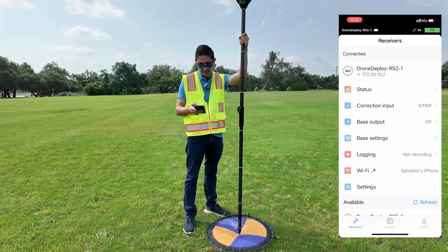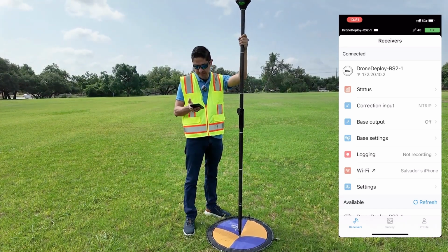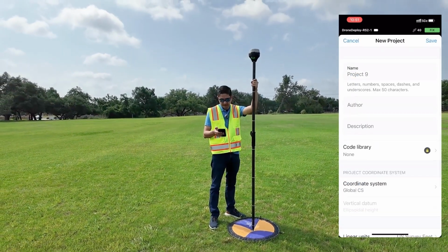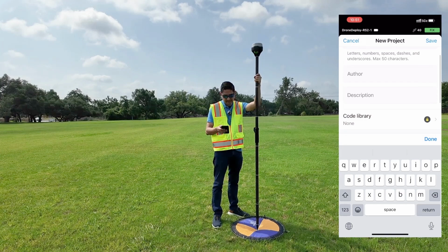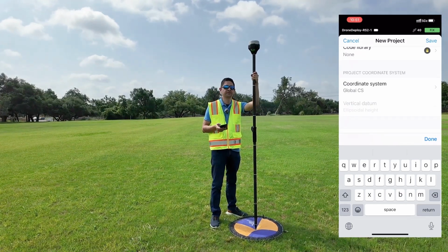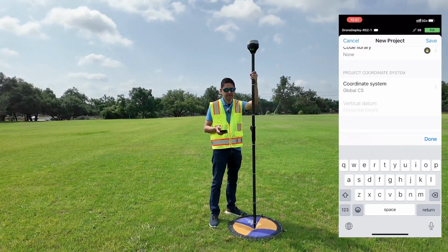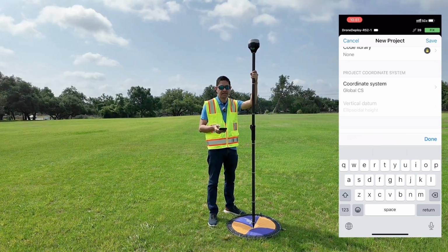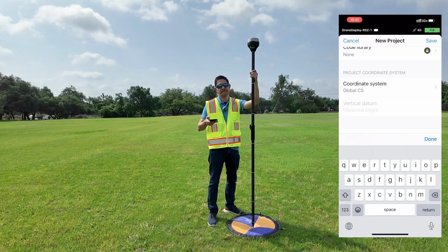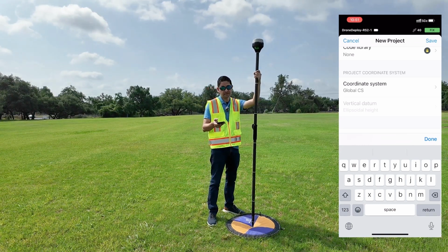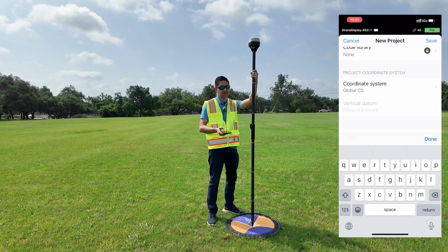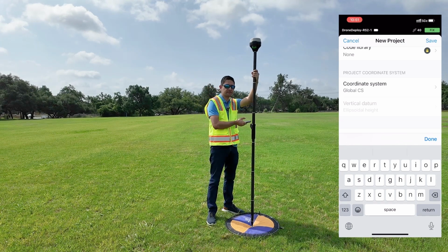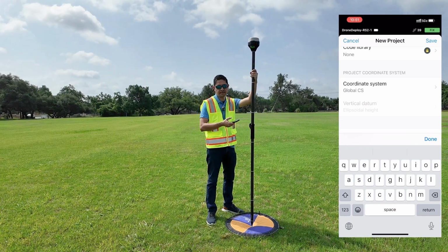Now, to start surveying your points in Emlid is super easy. You just have to start a survey. You create a new survey, and here you're going to give it a name. Now, besides the name, the most important thing is going to be your coordinate system. The best way to define your coordinate system is by identifying the EPSG code, and just make sure that you're surveying in a code that you're actually going to be flying and processing in DroneDeploy, but also, if you're going to be using the data outside of DroneDeploy, to have that same code on whatever design files projection system you're using. So it's very important to have cohesiveness on the EPSG code throughout the life cycle of the capture.